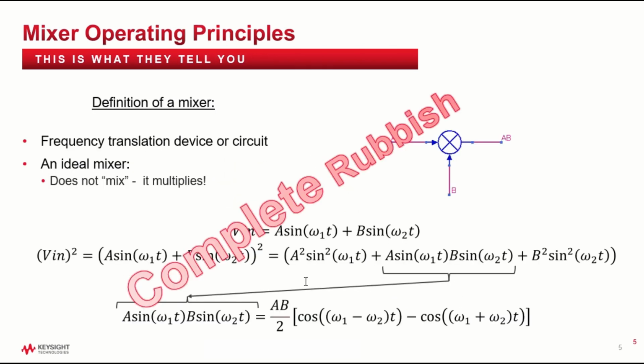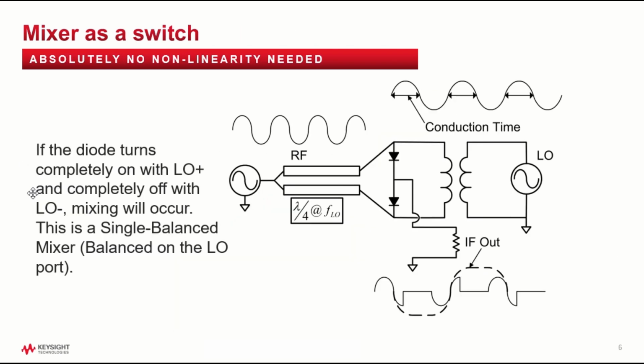then they tell us, oh, it becomes a sine. You take two cosines, you square them, and then someplace out of all that math drops the difference between two frequencies. And this is not the way mixers work in practice. I have never seen a mixer that operated this way. An ideal mixer, it doesn't actually mix, it multiplies. It multiplies essentially a chopping signal from an LO.